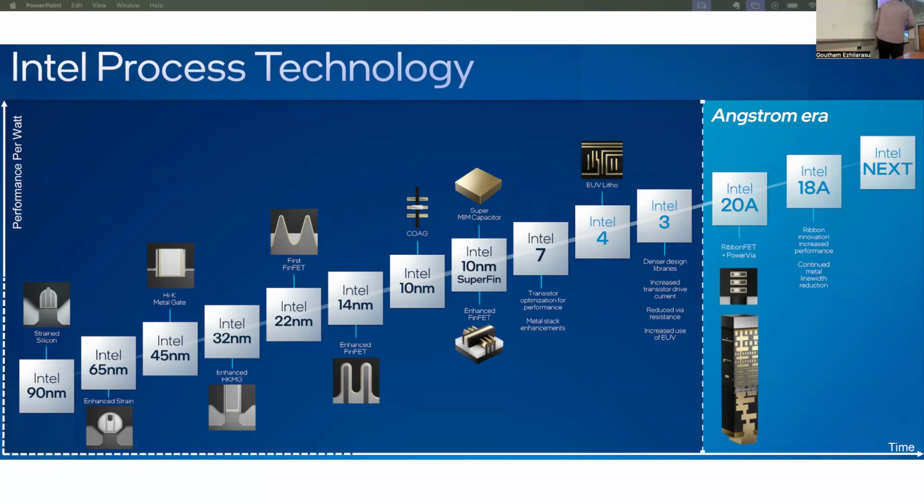That's why when going from this technology to this technology, you suddenly get a very different kind of cross section, right? With the oxide going all the way around, because this is a replacement gate process. And then once you went further and further, this no longer holds. It's difficult to scale a structure like this. And so the only way that you can continue Moore's law scaling and get performance out of the transistor is to increase the width of the transistor, but you don't effectively increase the area of the transistor. So the only way to do that is to go vertically up. So that's where you end up having these fin-like structures.